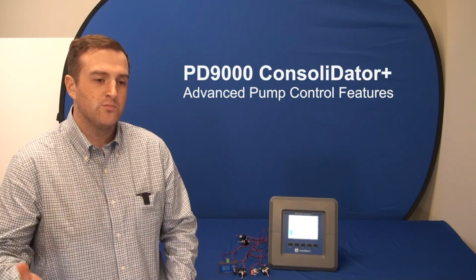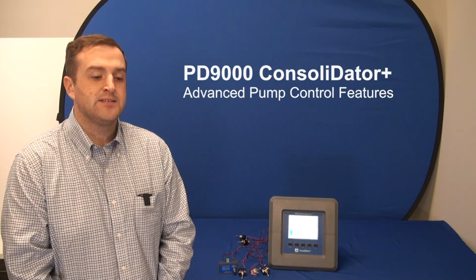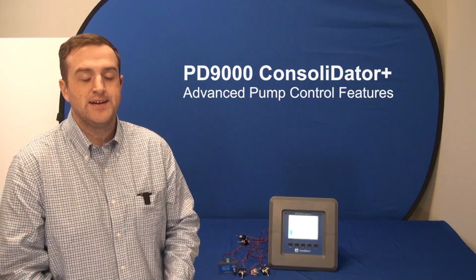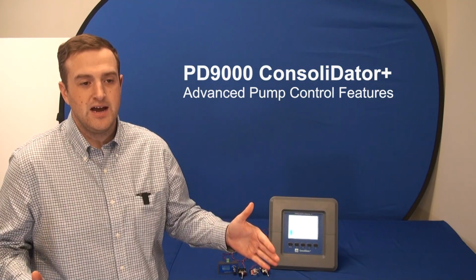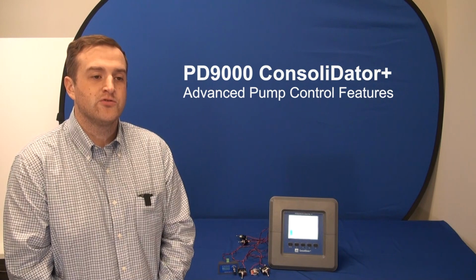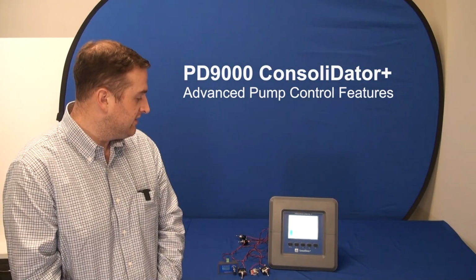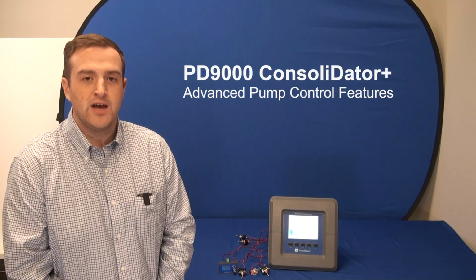There are float backups, a low float, a mid float, and a high float. And then we're looking at pump bearing temperature and a leak seal, as well as motor ramps. Additionally, we're tracking the maximum amount of time when a pump has not run, and then we're also tracking the number of pump cycles per hour. So all of that has been set up and is configured here, and we'll just go through and explore that a little bit.